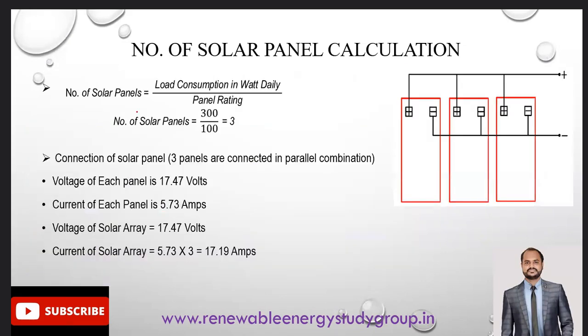Now, once we have selected this panel, the formula for the total number of panels we have to use in a system is the total load consumption in watt on a daily basis. The capacity that we have calculated is 0.278 kilowatt, so the overall plant size is about 300 watt on average, divided by the panel rating of 100, and from this we get the answer as 3. Once we have calculated the total number of solar panels, we have to consider how exactly we connect these panels in series and parallel combination.